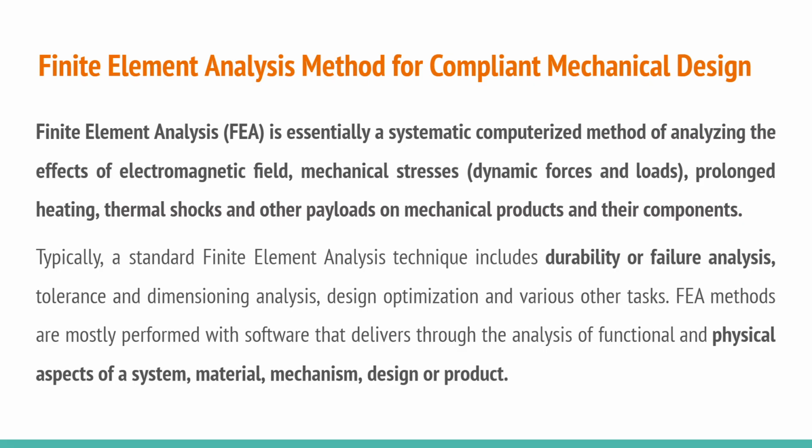Finite element analysis, FEA, is essentially a systematic computerized method of analyzing the effects of electromagnetic fields, mechanical stress, prolonged heating, thermal shocks, and other loads on mechanical products and their components. Typically, a standard finite element analysis technique includes durability or failure analysis, tolerance and dimensioning analysis, design optimization, and various other tasks. FEA methods are mostly performed with software that delivers analysis of the functional and physical aspects of a system, material, mechanism, design, or product.